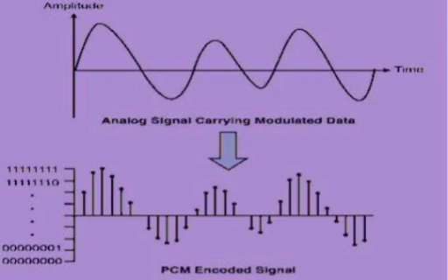Parity check. When the number of check bits is 1, it is known as a parity check code. It is of two types. Even parity check code: if the check bit is such that the total number of ones in the code word is even, it is an even parity check code. Odd parity check code: when the check bit is such that the total number of ones in the code word is odd, it is called an odd parity check code.